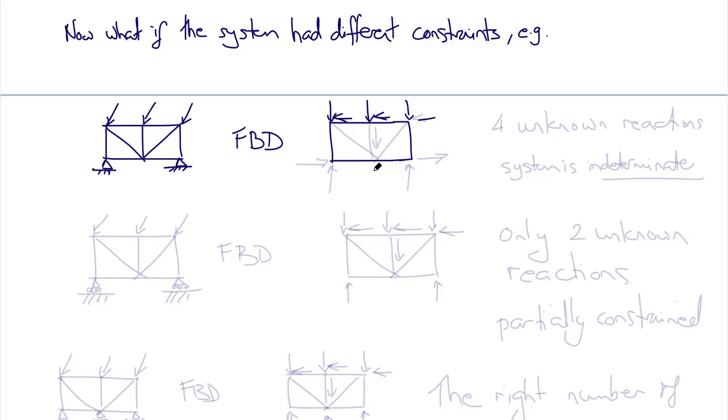We have the same applied force components, including the load due to the weight. And we have the same x and y components of reaction forces at A. But now on B, we have x and y components of reactions, so we have 4 unknown reactions and only 3 equations, so the system is indeterminate.